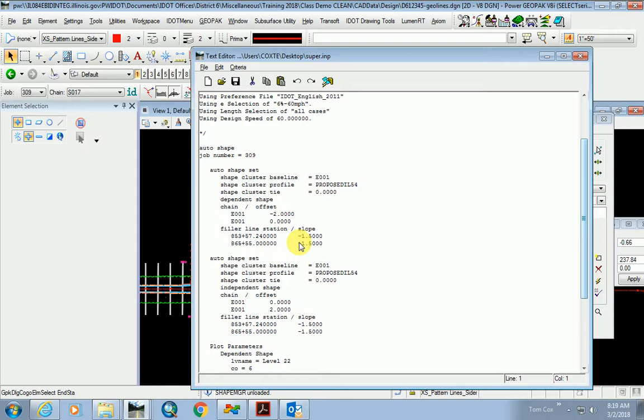And then at some point, 10 years ago or something, they changed it. So now it's roughly, but not exactly, 3/4 off the curve and 1/4 on the curve. But there's a diagram that we have that shows the super elevation transition development, with all the critical points within that transition development.